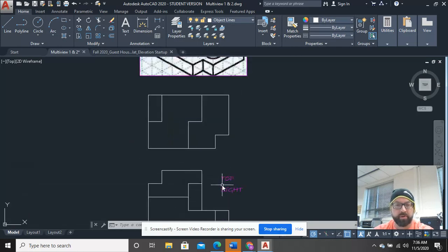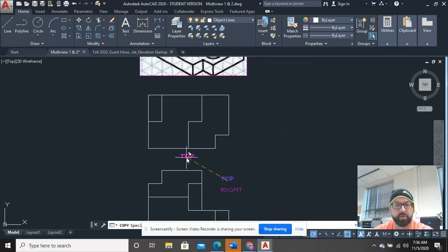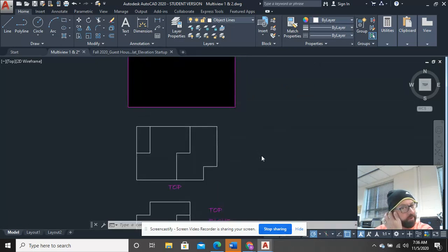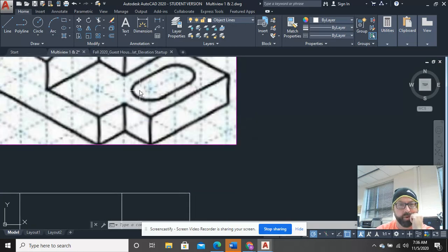So we've now constructed the top view, except we're missing one thing, and this is usually the area that students kind of go wrong with this, okay? So we have this slot that has to get drawn, okay? And really, this is an arc, and if you look at that arc, it is a 1-inch diameter, okay? These are all inches, and that completely corresponds. So rather than trying to figure out the position and the radius of the arc, if I can tell that that's 1, I could just use a 1-inch circle and a 1-inch circle.